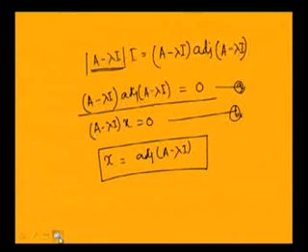By using MATLAB also you can very easily find the eigenvalue and eigenvector of the system. In MATLAB you have this function. You have this matrix M and this matrix K, where M is the mass matrix and K is the stiffness matrix. You can write the code like this. First find A, so A equal to inv(M) multiplied by K.